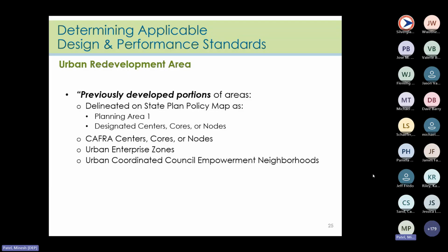So if the reviewer finds that woody vegetation has returned to areas of a previously developed site, the exemption is not going to be allowed. The reason being is that removing woody vegetation and putting new construction over this portion of the site is going to result in a loss of groundwater recharge. And then the reviewer can check the NJ GeoWeb to determine whether the rest of this information is applicable to the site.